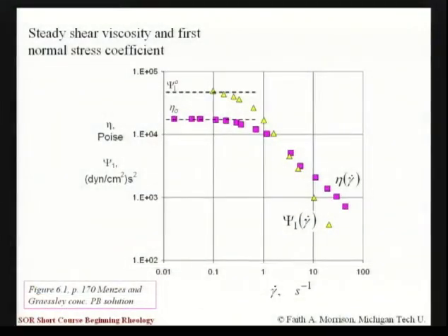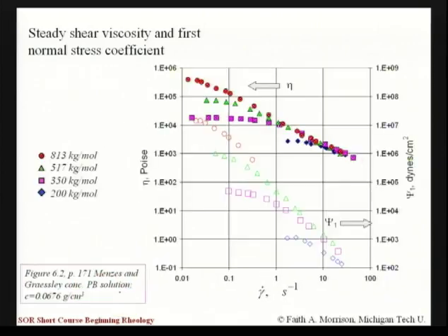So we've looked at a few examples of how materials behave, and what we see very clearly is that the Newtonian predictions are not valid. There are many materials for which it is valid. Newtonian predictions are valid for water, oil, and air, but they're not valid for polybutadiene solutions. They're not valid for these polybutadiene solutions at a variety of molecular weights.